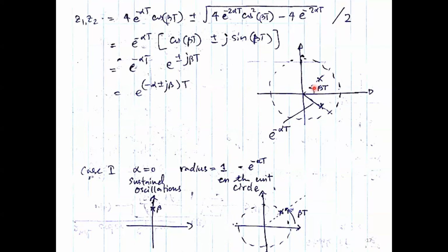And the sampling angle is less than 45 degrees or so, right? Which means you can have how many of these angles in one cycle? Say 1, 2, 3, 4, 5, 6, 7, 8. 8 samples in one cycle, right? If you just assume this as 45. So that is enough samples to capture signal variation.